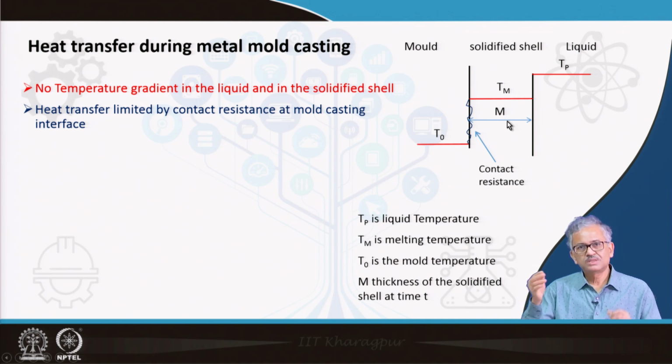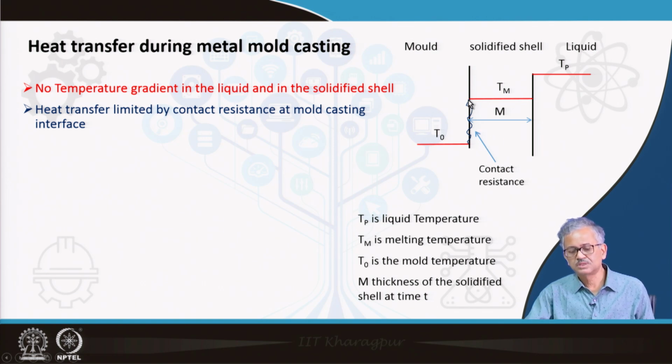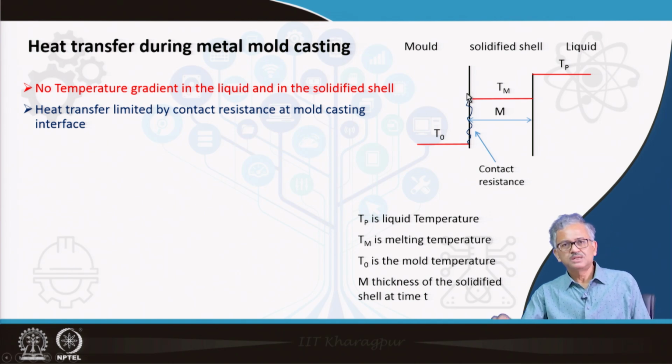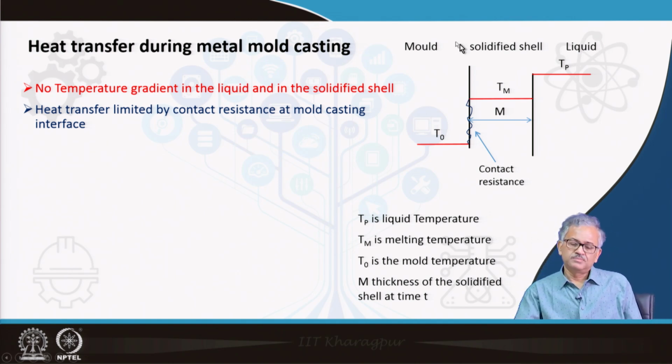So as a result, when the steel shell solidifies, when the liquid solidifies over the mold wall, there are a lot of gaps, asperities, and gas pores. That basically detaches the casting from being molded with the metal mold. So, we can consider that there is a contact resistance. There is a huge resistance there.